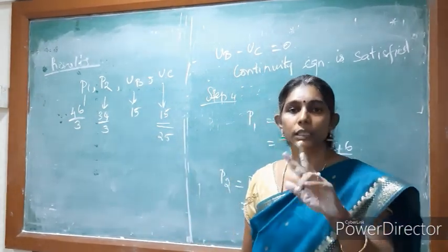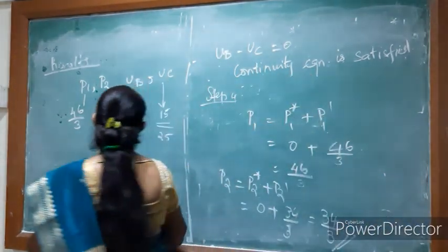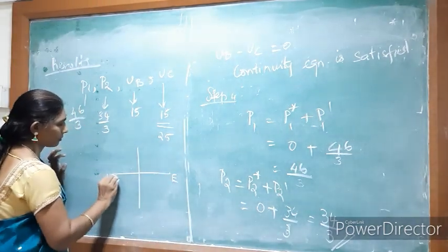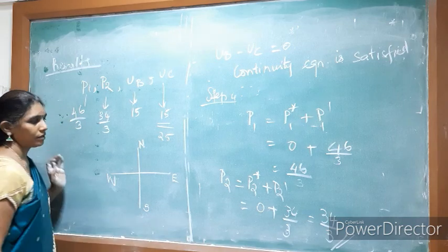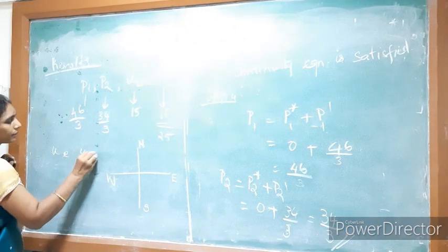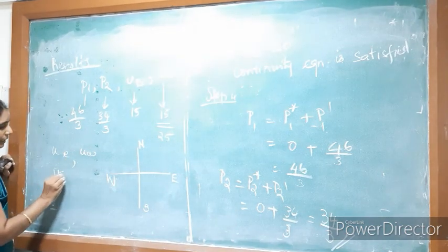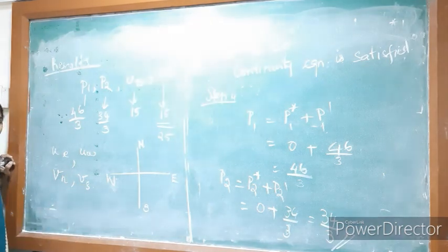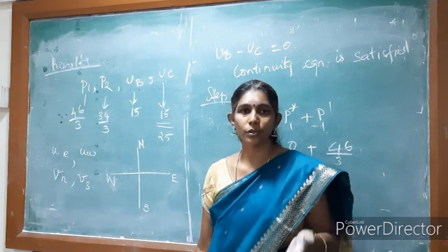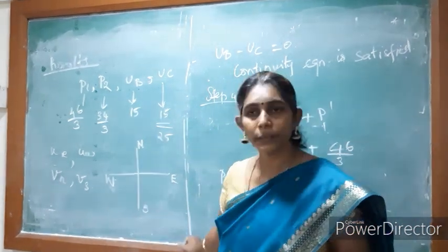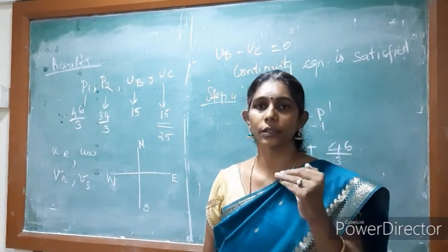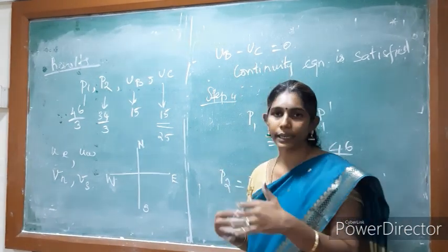So if you are going to consider a two-dimensional problem, that is U and V, we have seen this figure earlier. So if this is the case, then I'll have to calculate not only U at E and U at W, but also I have to calculate V at N and V at S. You can try one such problem. I would advise you to just go through Patankar textbook, so that will be useful, or John D. Anderson. You can refer any of the textbooks that you're comfortable with. Just try out a 2D problem and see how many iterations it's going on.